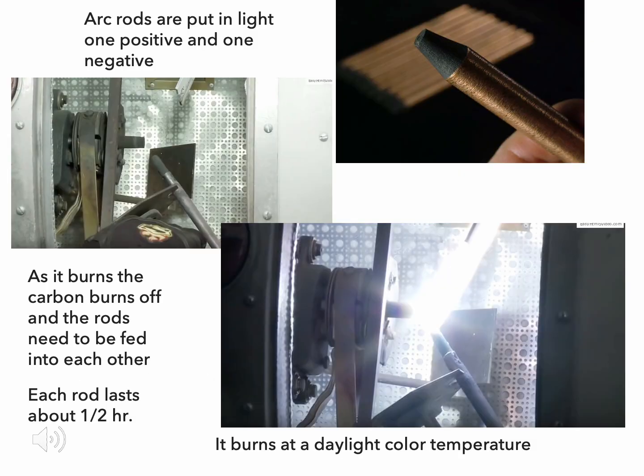There are two rods in the housing, one negative, one positive. As the rods create the arc light, the carbon from the rods burn away, so there's a mechanism that feeds the rods together. It's the electrician's job to make sure that there's a proper gap between the two rods. The rods last for about a half an hour, and then they need to be replaced.